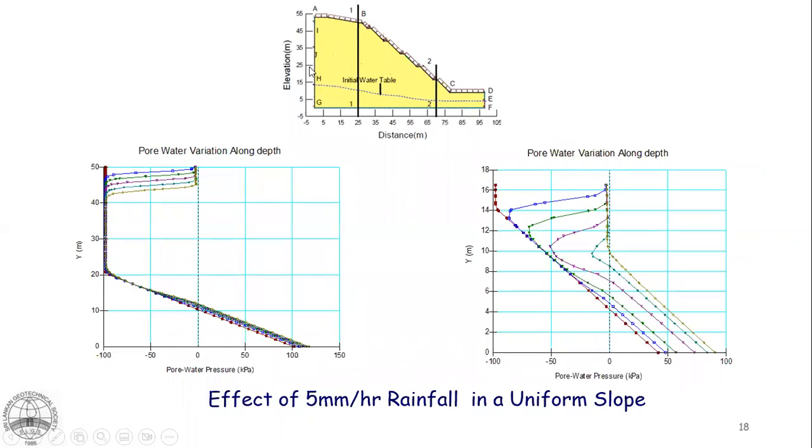So in the case of uniform residual soil formation with the rainfall, first day matric suction is lost up to that depth, second day further deeper, and like that for the 5 days. So then the water that infiltrated through the saturated pores has caused a slight increase of the groundwater table. So this is in section 1.